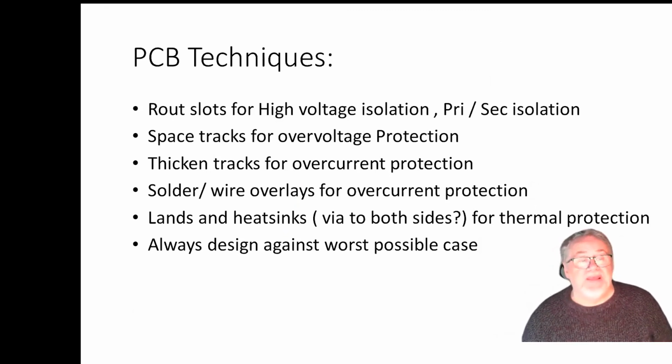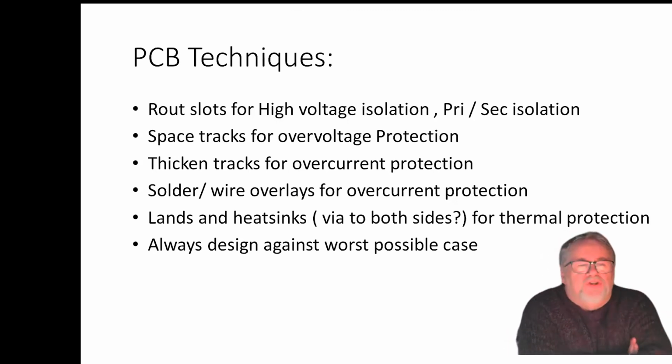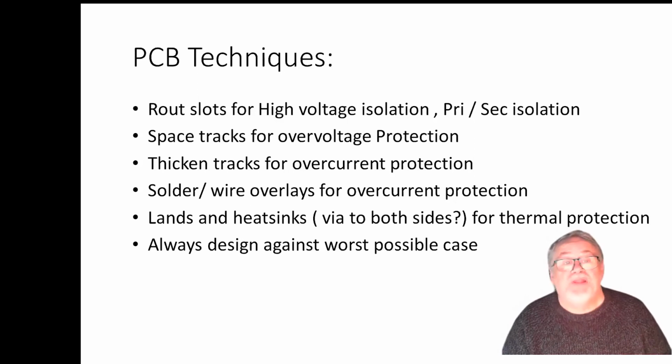Finally, on PCBs, I've already mentioned routing. In PCB talk, there's two words, route. You route tracks, you make them go from A to B, and then there's routing, where you route slots with a router, which makes a hole in the board. It's very easy to get the two words mixed up. I use route without an E for the whole thing, and route with an E for putting tracks down. You route slots for high voltage protection, to isolate high voltages and to keep the primary and secondary circuits apart.